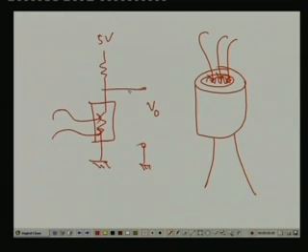In dark it is very large resistance, around 2 megohm, in the bright light it is very less, 20 ohm, clear. In fact, in the dark it should be very high, it should be infinite, but there is always a dark current, because there will always be some thermally generated electron hole pairs. So, there will be some current, right.